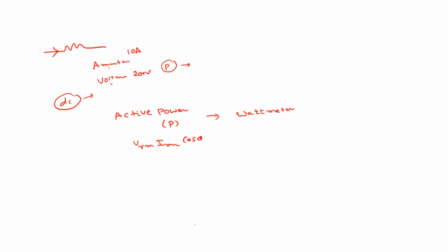Have you studied this earlier or have you listened to this earlier? No, sir. So this power can be measured by using a wattmeter. This measures only the active power, right? In watts. If the reading of this one is 700, that means the active power consumption is 700 watts. From this, you have other things, like calculating the reactive power or the apparent power. So that can be done. Okay. So this wattmeter will measure the active power.